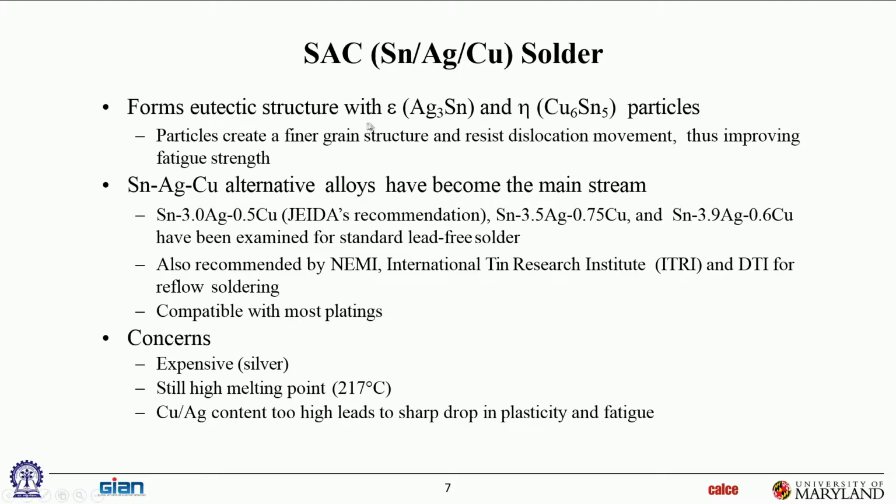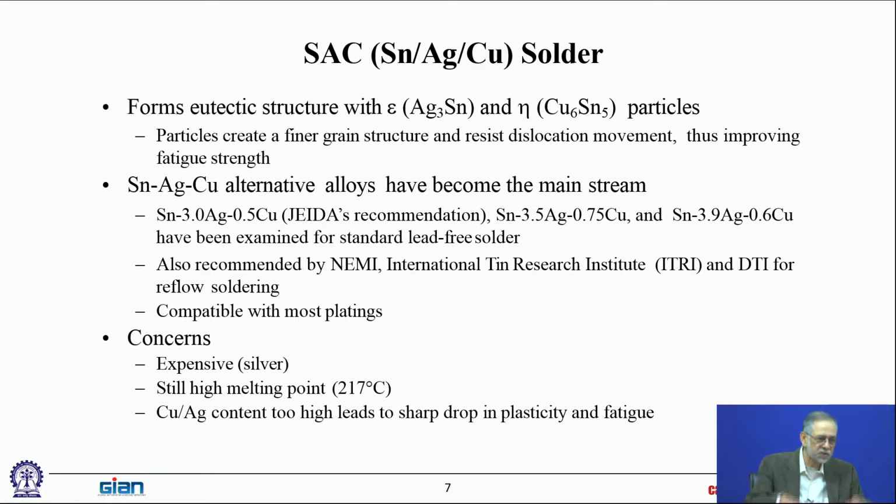Okay, so we'll talk about the microstructure a lot. It's basically a tin matrix, dendritic tin matrix. Okay, the tin solidifies in the form of dendrites, which are complicated structures. We'll talk about it. It's like Christmas tree kind of shapes. That's what it really looks like inside. If you look at tin with a microscope, really zoom in, it's not just a bulk homogeneous structure. It's got all these dendritic elements in it, and dendritic forms in it. And that has to do with the way it solidifies, the way it crystallizes during solidification.